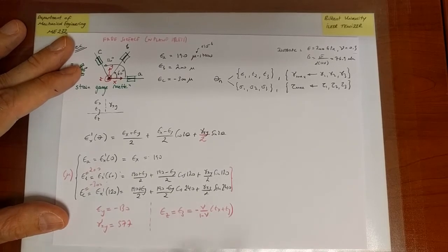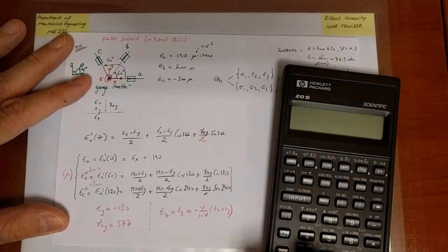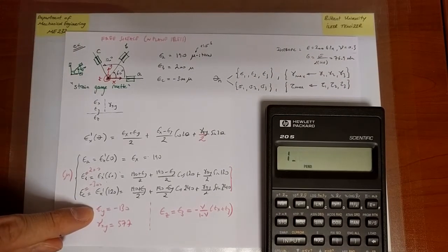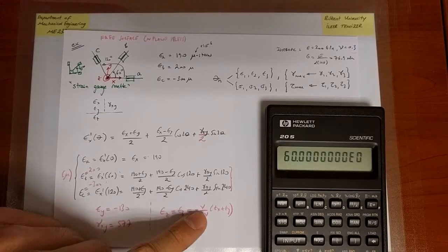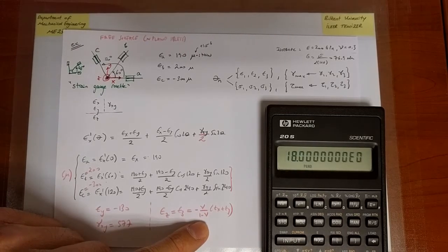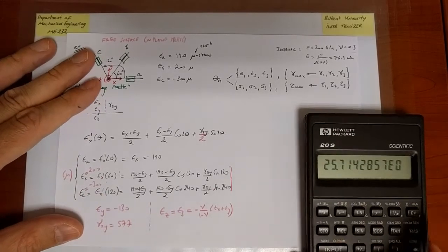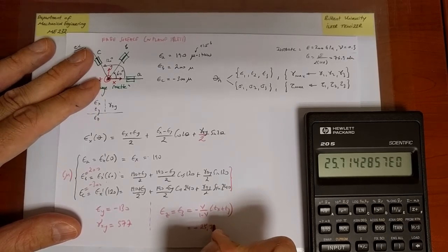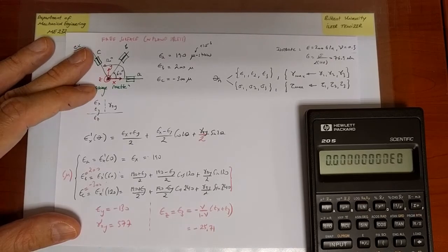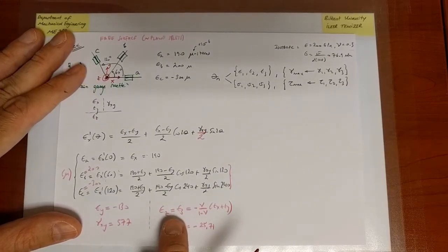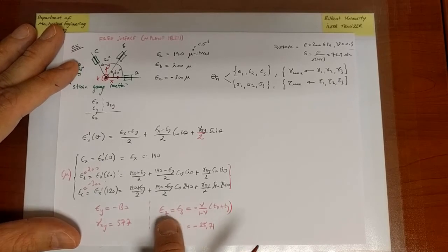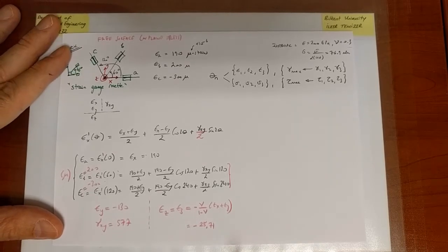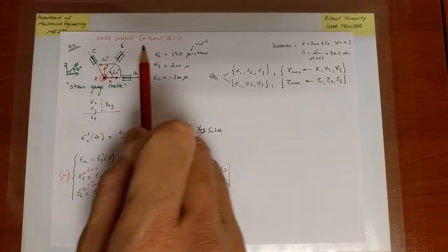Okay, so if you go ahead and calculate that, we would obtain epsilon x, which is 190, plus epsilon y, which is 130 but negative. And then we multiply it with 0.3 divided by 0.7, and we would obtain a negative 25.71 microstrains. Again, goes without saying. So I know the third value of the strain. Remember, gamma zy and gamma zx are both 0 because it's a state of generalized plane strain. Why? Because of the fact that we have a free surface.